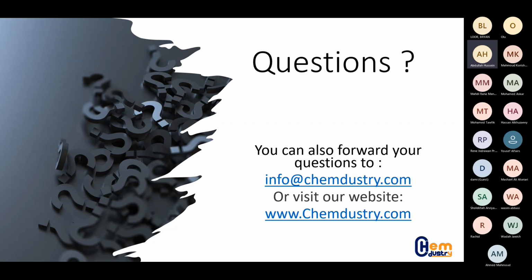In prediction, should we use total iron content or dissolved iron, since too much iron sulfide in the system will affect the inhibitor efficiency? I would recommend the total iron content, since, as you said, the dissolved one might not represent the system, but that also still depends on what you are trying to do scale prediction for.